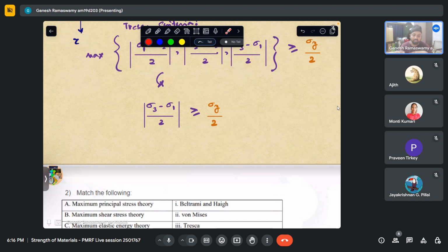So considering all this, there are certain steps where we will be bringing in some factor of safety. So generally, we will not be comparing it to this value, but a factored value of this. So this will be multiplied by some factor here, which will obviously be less than 1, in order to compare it with not maybe 100%, but 80% of the value and so on. So when we multiply that, we will have a factor of safety coming into the picture.